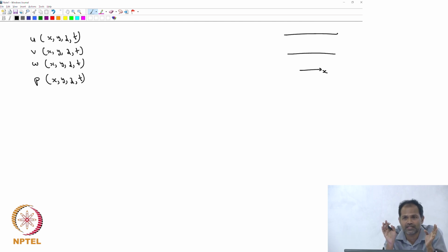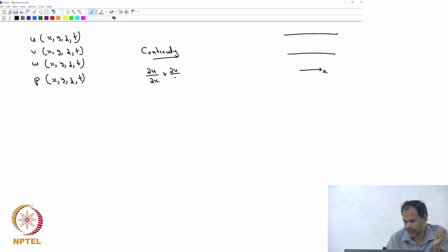So that tells us that for the governing equations that we use, we can't do all those simplifications that we had used earlier. So we need to invent something better. Can we invent something better is the question. Let us write down the continuity equation and the momentum conservation equation. These are the two equations that we had, and we just kept on manipulating them. The continuity equation in Cartesian coordinates was just dou u by dou x plus dou v by dou y plus dou w by dou z equal to 0. And we had the momentum conservation. Let us write down the x momentum equation.